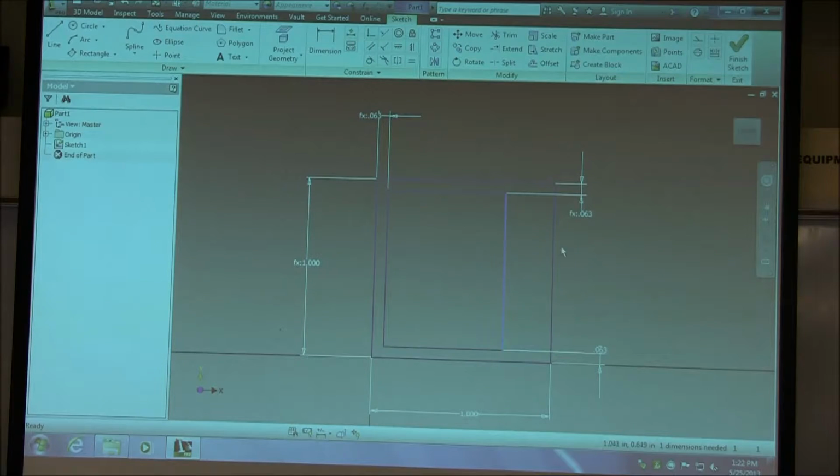So I can drag it on the inside and add in a dimension here. Set it equal to this guy. And then now I have the right shape. I have a box inside of a box, and I can use that to make a solid piece. Because that's really what we're going to get to with all of this, is we're trying to make solid pieces out there, representing tubes, wheels, motors, whatever you need to make to put on your robot.